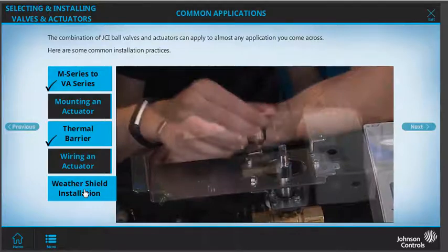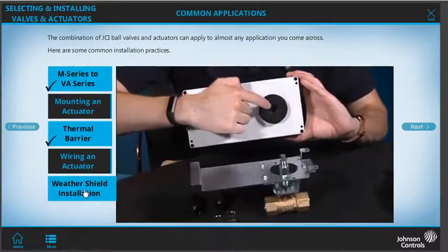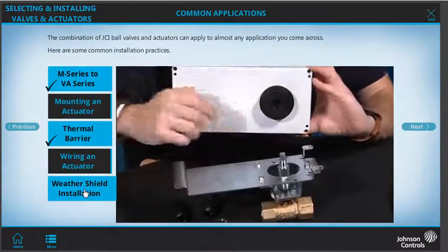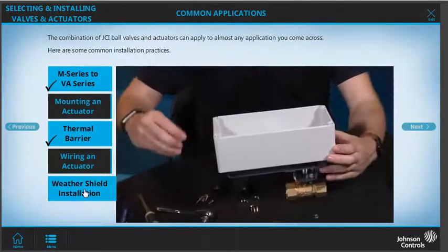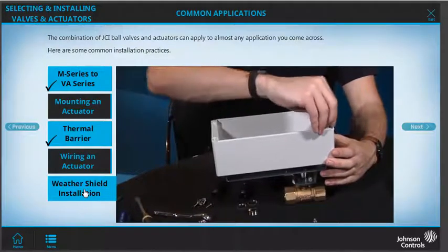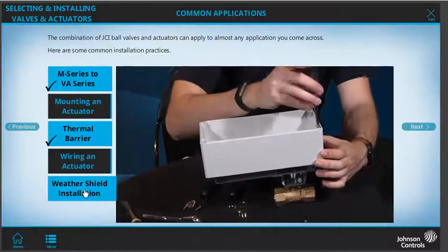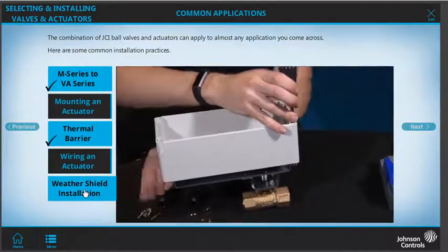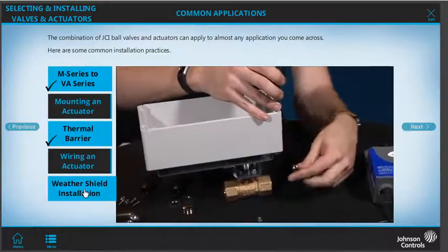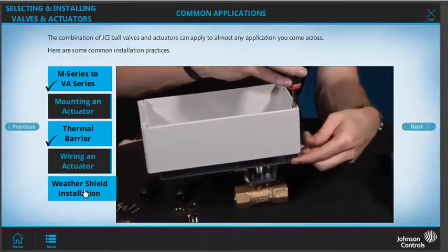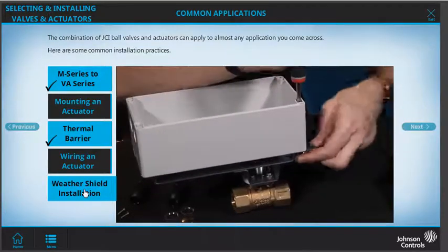Install the weather shield base and seal assembly on the weather shield enclosure mounting bracket. Secure using the 4 number 6 half-inch screws and nuts in each corner using the Phillips head screwdriver and 11/32 inch wrench. Tighten the screws to a recommended torque of 9 to 12 inch-pounds.